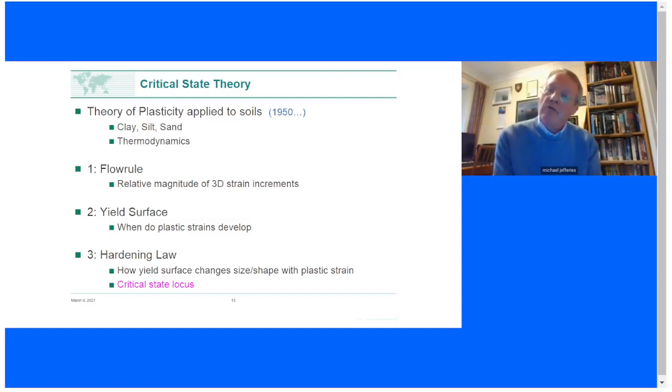But you never really question whether you learn the most from loading. The key observation that drove people was that if you do a triaxial test on clay, for example, and bring it up to peak load, then take the load off, you don't get the deformations back. The deformations are more or less permanent and irrevocable.